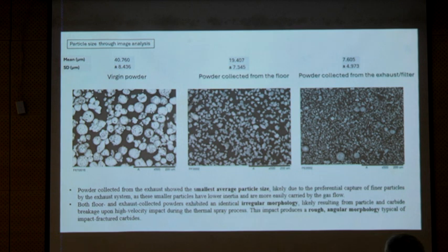What I started saying was, from some other supplier, we see chunks of alumina here and a little bit here. Why do we see alumina? Some of you work in thermal spray. Why do I see alumina along with my tungsten carbide? Correct, because they use alumina for grit blasting, so that is also falling on the floor. Sometimes that's also getting collected in the exhaust.